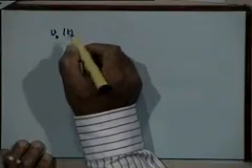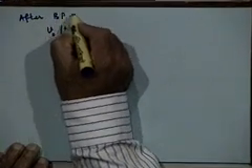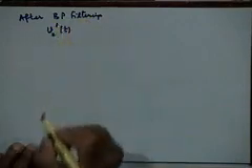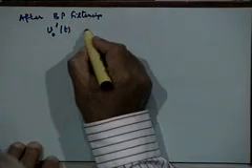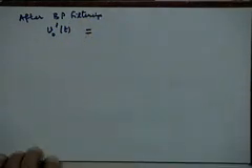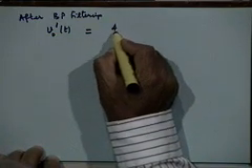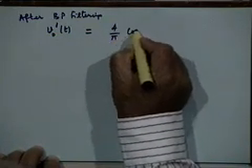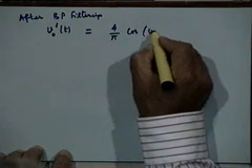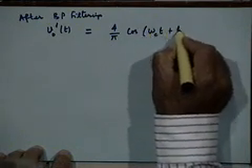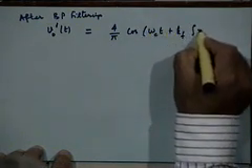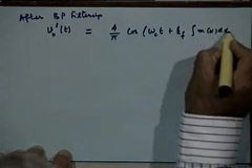and therefore your V naught of t after band pass filtering, let me call it V naught prime of t, right, would be only the first term of this Fourier series, which is 4 by pi cosine of omega c t plus k sub f integral m alpha d alpha.